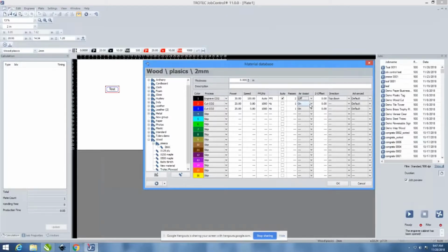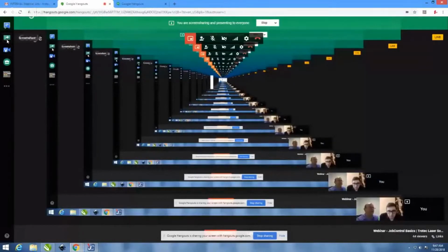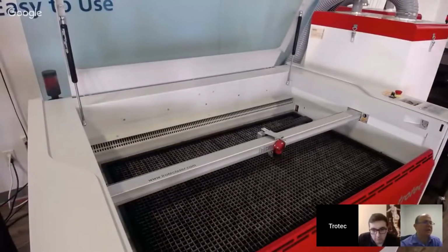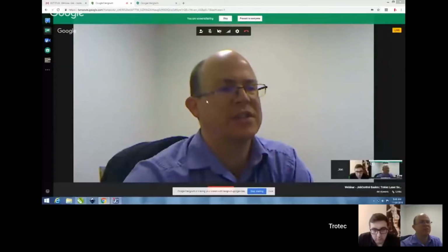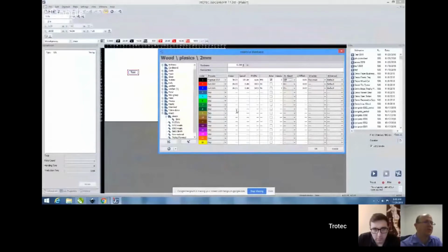So if you have the nozzle on the laser head on a Speedy 300 or a Speedy 400, basic rule of thumb is if nozzle on, air must be on. If the nozzle is off, then it doesn't matter as much, but nozzle on, air must be on. And if you try to have the nozzle on and no air, that nozzle will basically act almost like a scoop, and it can pull smoke up onto the lens and you can damage it. So it's very important that if you're running the nozzle, you have the air on to protect the lens.